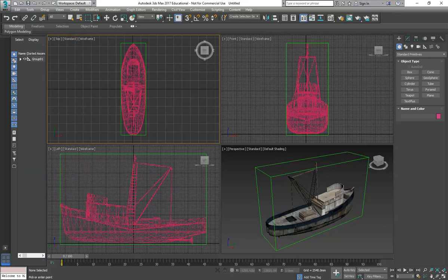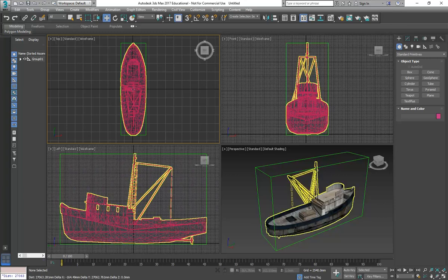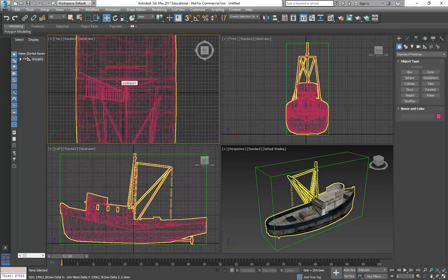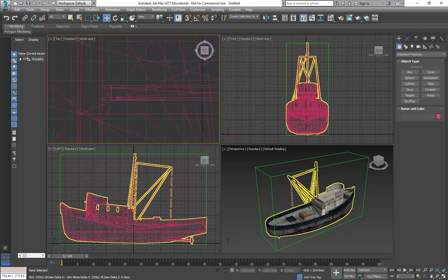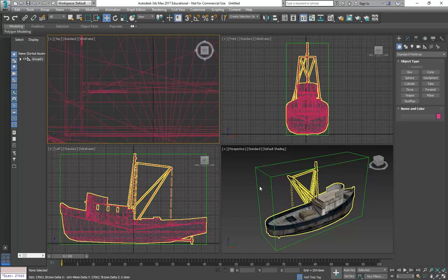And so there, I'm going to double click in the top view and then click once to give the second point. And that's how you use Measure. So you can see there again now the distance on the status bar at the bottom is 27 metres. And again, I think that's about right, but maybe I'll zoom in and see if I can find a door. So it looks like a door in there, or is it?